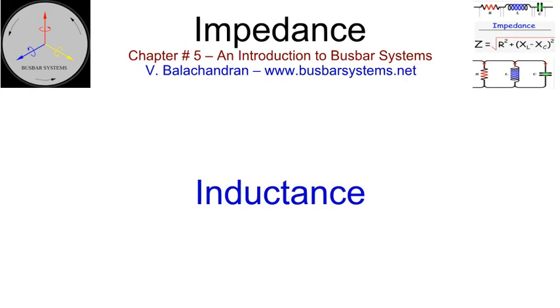Inductance. The inductance in busbar systems is normally not of much concern for system engineers. The values are not significant when compared to overall values to alter any system parameters for calculations of fault currents and voltage drops. Evaluation of reactance is important in AC high current open bus as in the case of induction and arc furnaces, and long length of low voltage bus duct connection between the transformer and the incoming switchgear panel.